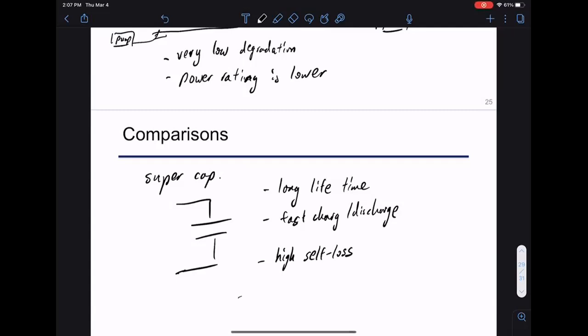This has applications in wind turbines. Before, we said we're dumping power through a resistance in a wind turbine over hundreds of milliseconds. You can replace that resistance, for example, with a supercapacitor. Instead of dumping to a resistor, you dump to a supercapacitor, and if the fault clears relatively quickly, you can recycle the power back to the grid, so you don't have a loss.